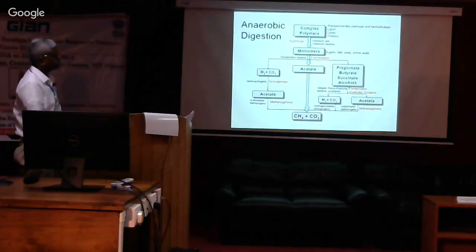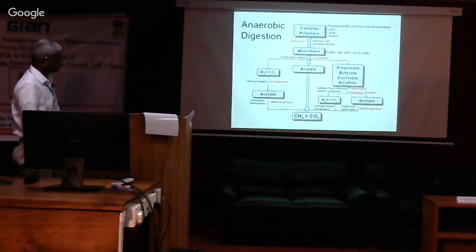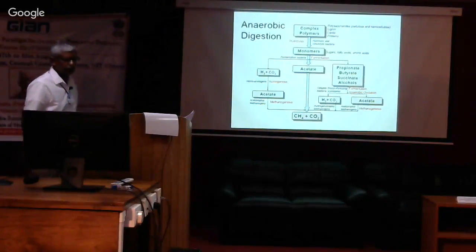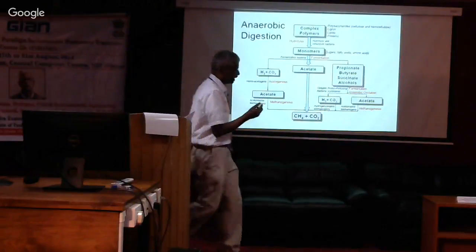So you take this, and this is of course all done by microbes. And this is not just one microbe, this is a microbial consortium. So one species in the consortium takes this and ferments it directly into acetate. And then we go through what is known as acetate cleaving or acetic acid cleaving, where acetic acid is partitioned into carbon dioxide and methane.